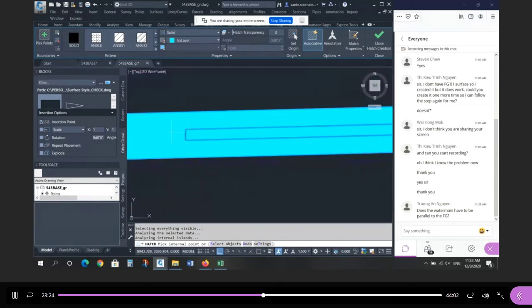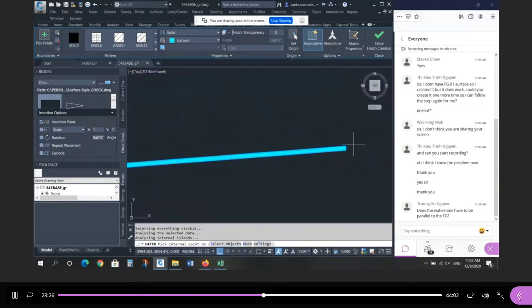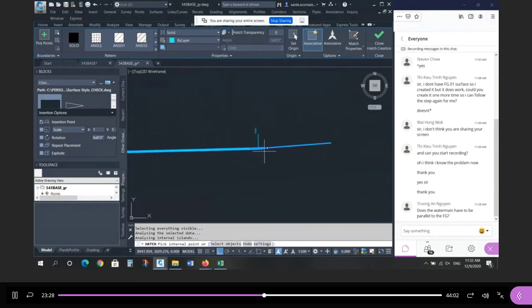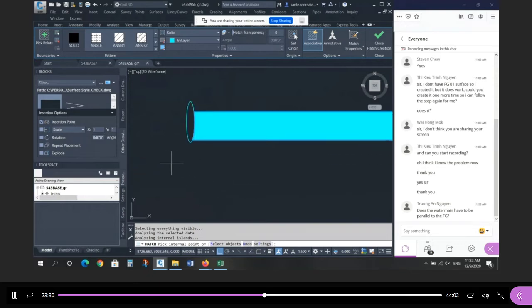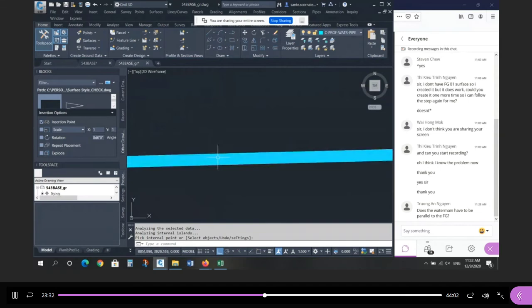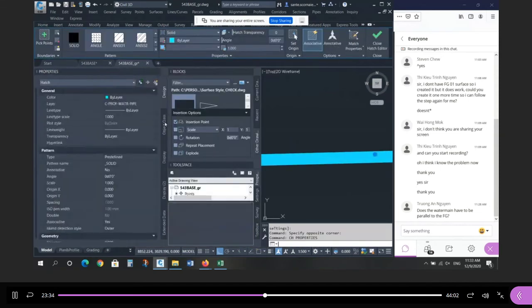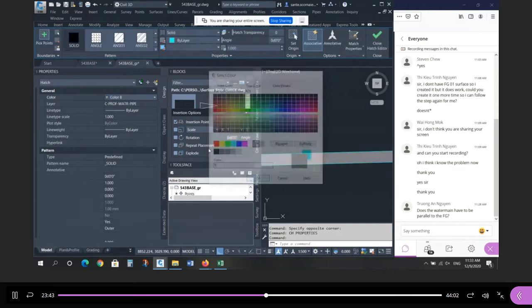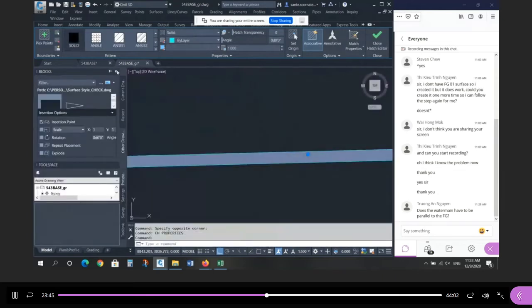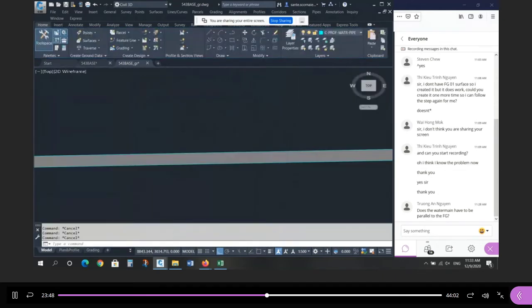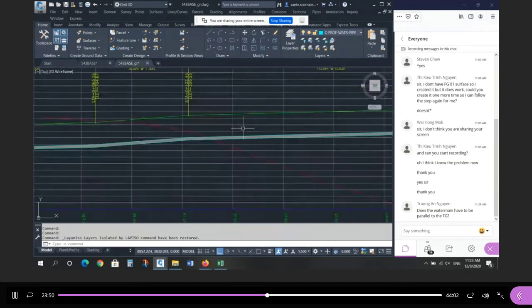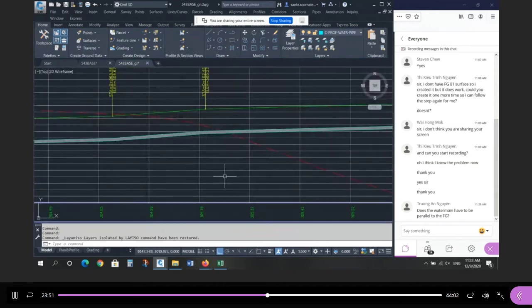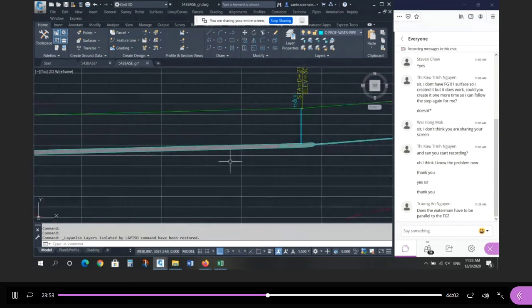The holes I would show unhatched. I wouldn't hatch that, and I probably wouldn't hatch this at this end. I'd leave that open, and I'd leave this open as well as a cross-section pipe. And then make it color 8. If I turn everything on, it starts to look a lot like that one we were just looking at.